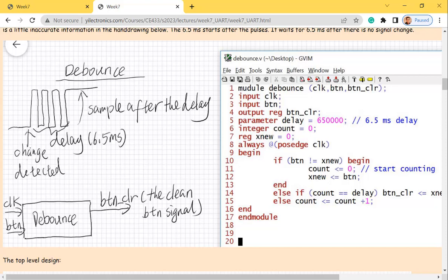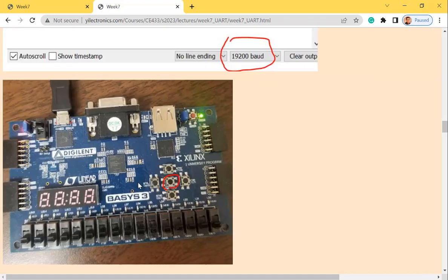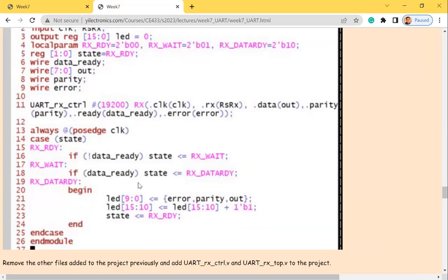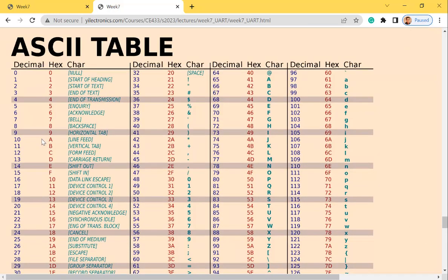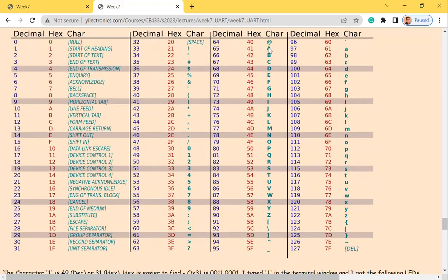And if you push the push button once, I'm trying to send a letter through the TX module to the serial monitor on the computer, so I can see a letter A in there. Okay, I push it, I send the A, and I push it again, I send the B, or whatever comes after that A on the ASCII lookup table, right? Let's look at it first.